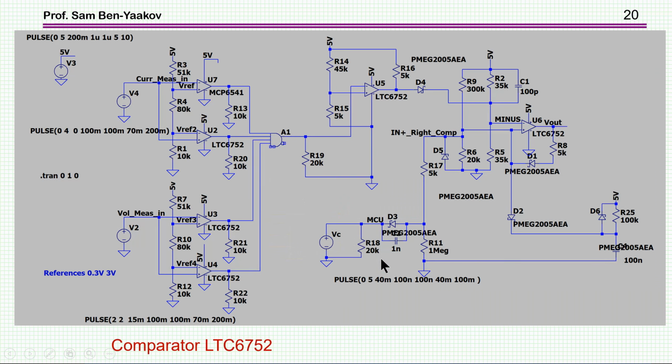So here is the simulation model. Let me start with something that we have already seen. This is the flip-flop comparator, the locking comparator. This is the exact circuit that I've shown. This is the power on reset, and here we have the derivative, and then the reference voltage coming here to the minus side, and this is the comparator that I've shown, and here is the AND. Now this AND is coming from all these comparators, and these are for the two limits.